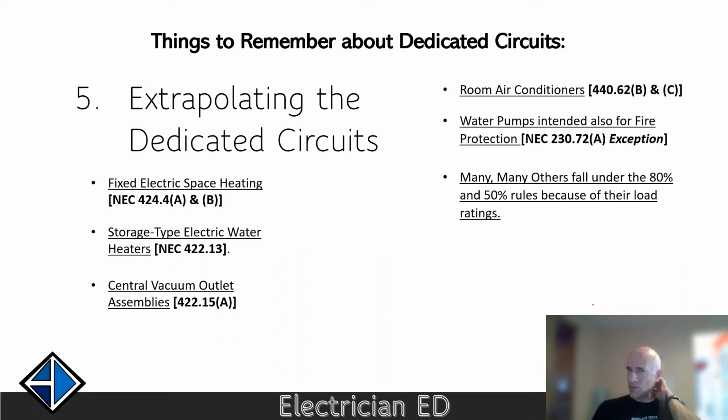So most places only have one single throw, and you can shut off all the electricity. But there is that special rule in the NEC that allows you to have up to 6 handle pulls to turn everything off. But they have to be grouped in the same area. And that's mainly for the convenience of the fire department, because they'll have to shut everything off when they're responding to a fire.